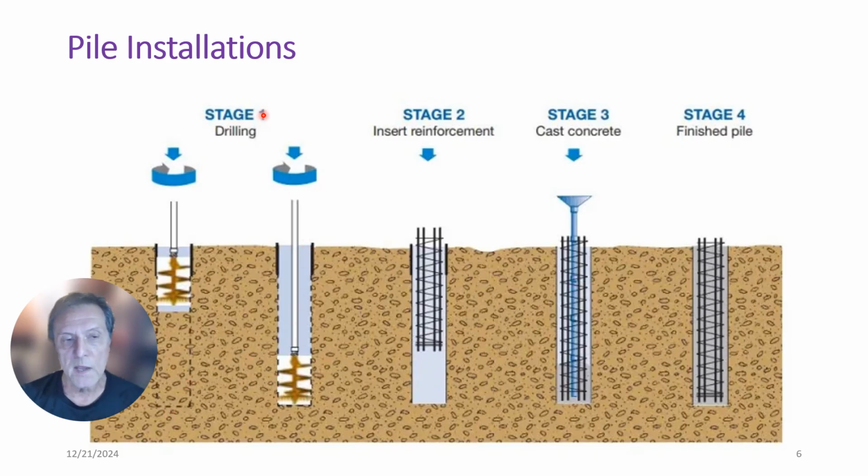And once the material is excavated out by drilling, a steel cage is dropped down for reinforcement. Cast concrete is then poured into the excavated boring and the steel cage. So now you have a structure of steel and concrete which provides hefty support for the structure up above.